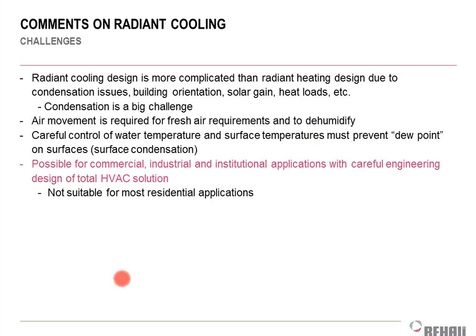So typically radiant cooling, whether it's in concrete slab stuff, or whether it's panels, or whether it's chilled beams or something like that, is going to have to be coupled with a dedicated outside air system to handle the latent loads of the space and the ventilation needs of the space. But you certainly can do radiant cooling, and we have done projects that way.